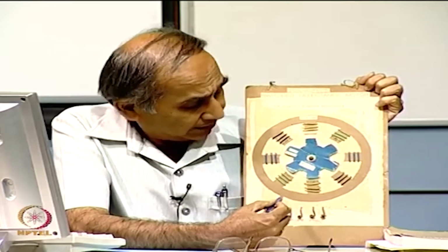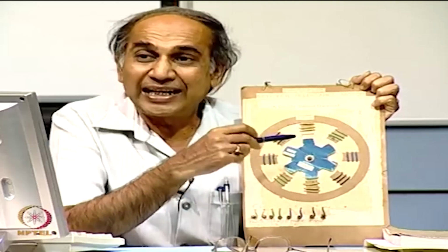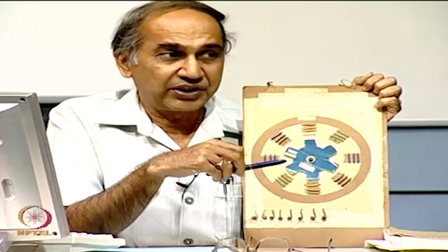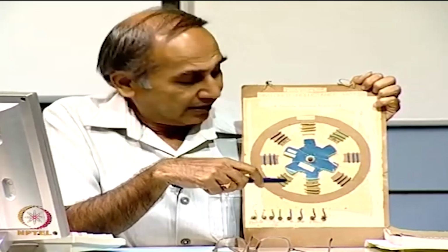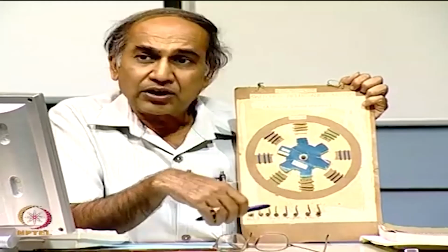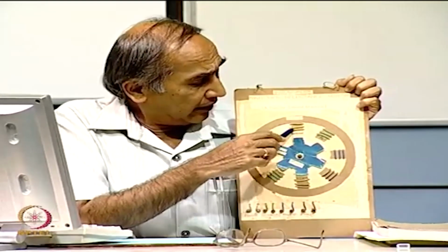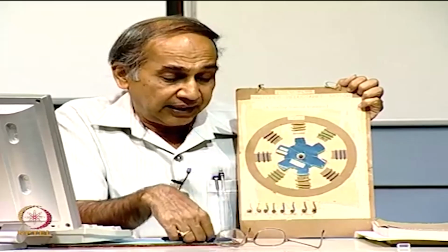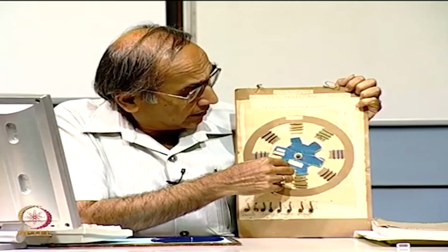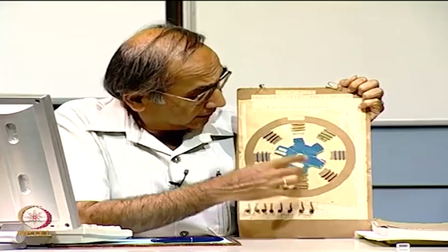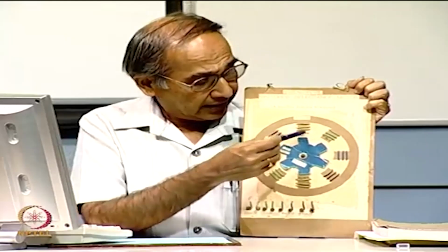So, that you have 4 coils and their terminals are brought out, you can have the yellow coil, the green coil, the blue coil and the black coil, okay, 4 coils, right, and they can be excited one at a time. So, you need 4 switches, for the same DC, your supply is DC. Supposing you switch the yellow coil, now the magnetic field will be aligned this way, and the rotor will align with this coil.